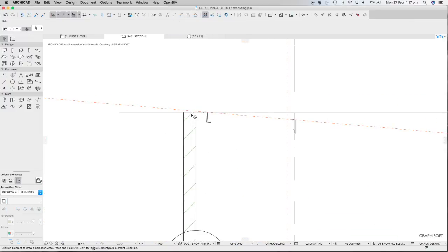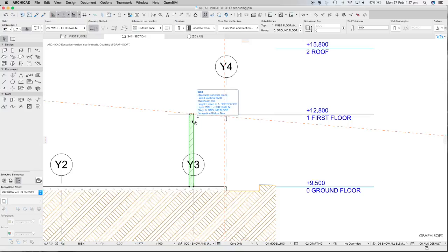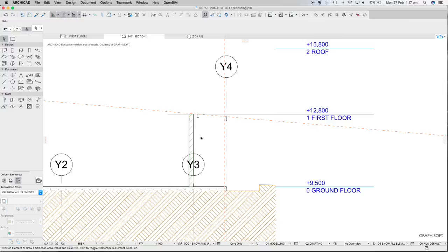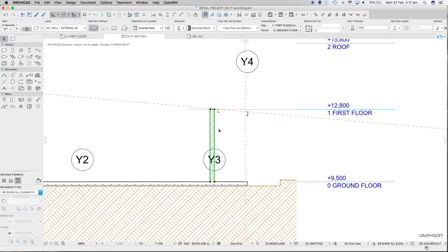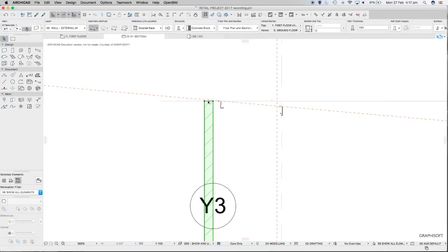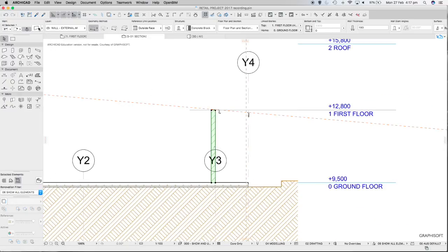Okay, so the top of this wall is set out at the top of level 1, so we've got to make some decisions here now. Level one was 3.3 metres. That might work out very nicely actually, because this wall, we probably want to change the height to be 3.2. So if you click on the wall again, no, looks like we might have to do that in 3D. Later on we can change it, or we can change it through here, I think.